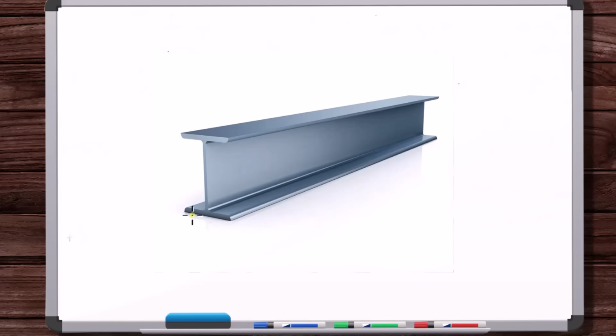Okay, now, so this is a point of contact. There is some load distribution here, right? A pressure distribution. You give two dimensions, which gives you a point on this surface, and then the output is a pressure value. There's some sort of pressure distribution here, and the volume under that pressure surface is the net resultant force. And then if you do the moments of area or moments of volume, you can get the location of the resultant force. But what's the pressure distribution?